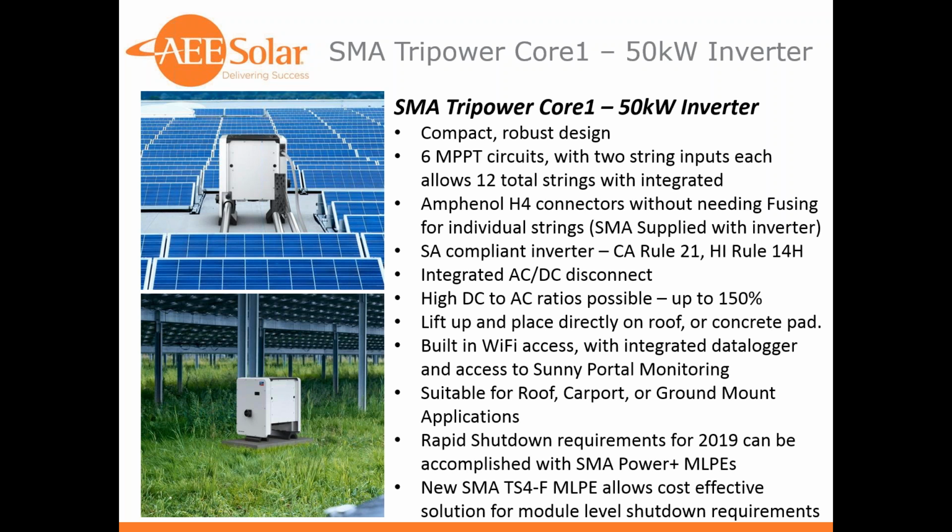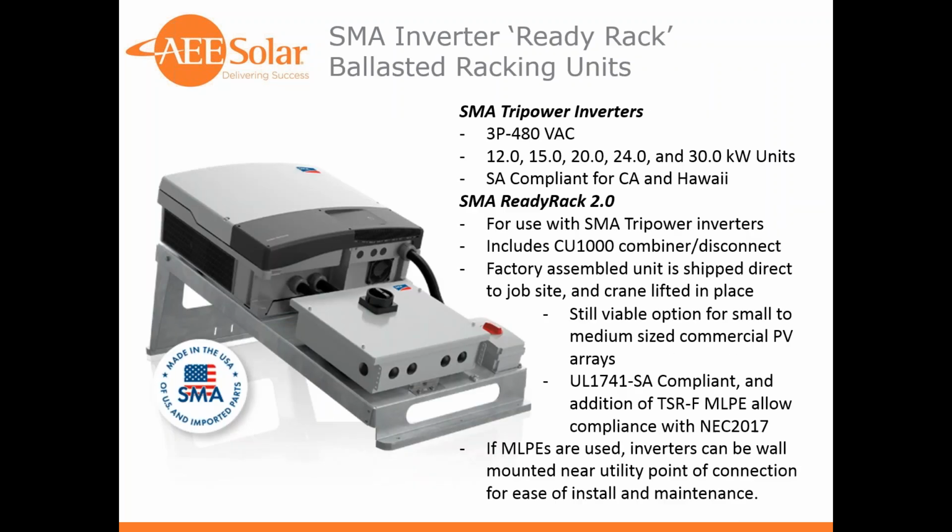Rapid shutdown. We mentioned before that with the Tigo branded, the SMA branded Tigo Power Plus optimizers, the new TS4-F would allow effective module level rapid shutdown. We still have inverters that can be mounted on ballast and racking. SMA inverters or the Fronius Simo inverters are still being used for medium to smaller commercial arrays.